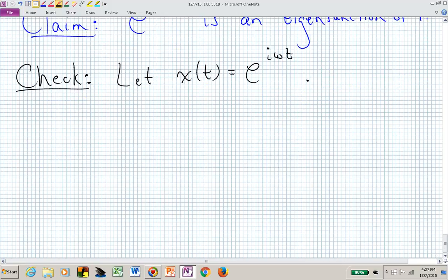And what is e to the I omega t? When I first start teaching circuits or signals and systems, and we start throwing around these complex exponentials, students go, oh, complex exponential, what do I even think? And I would just say, fix an omega, and now what do you really have? Now you have these rotating phasors, and you could just think of it as a combination of sines and cosines at a particular frequency, omega.